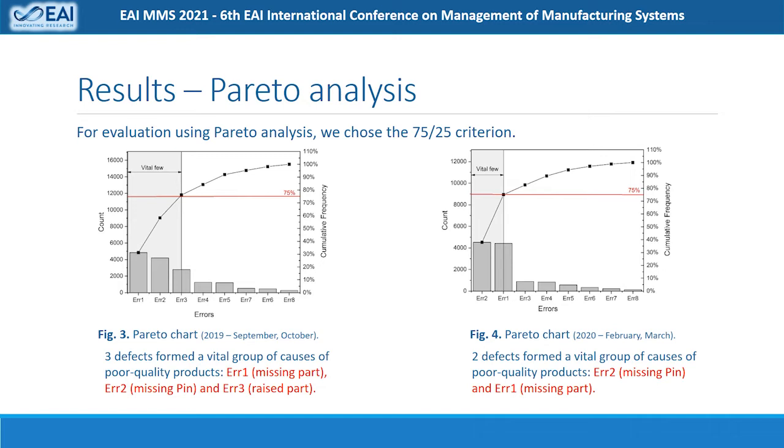An analysis of the production process showed that error 3 was mainly due to the cooler component, which has multiple connectors, is harder to install, and can get raised in the oven. For this reason, it was proposed to adjust the setting of the oven by changing the shape of the weights used to load the cooler before it enters the oven. The situation also improved with error 1, a decrease of almost 9%.